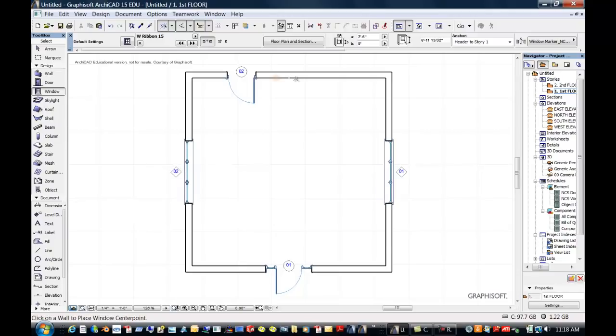And let's put that window in, and let's say that we want to go along this X coordinate again, so I'm going to put that window in. I'm going to do X, and I'm going to say I'm coming in the negative now, so let's do negative, let's do 6-6 again, and we end it with the plus, enter, and now we have that exactly over there. If we want to check on that, take our measuring tool, select here, and it was measuring to the midpoint. So if we go to the midpoint, that's 6-6. So that's perfect for us.